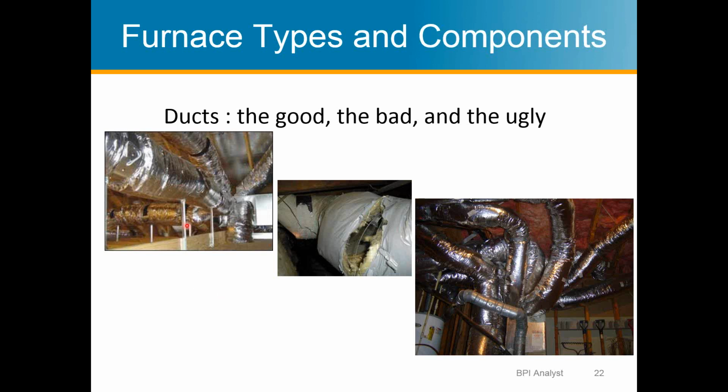They could be in a drop ceiling, which would be ideal, right? Basically, you would have the ducts inside the conditioned space. But leaking is still an issue, even if it's in conditioned space, although it's less of an issue. And even if they're in conditioned space, how tight the turns are still affects the efficiency of the system. It just gives more resistance.